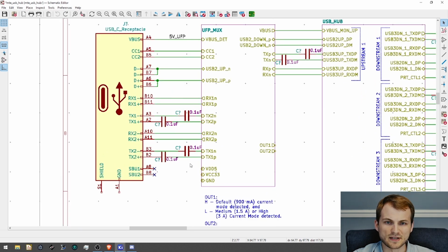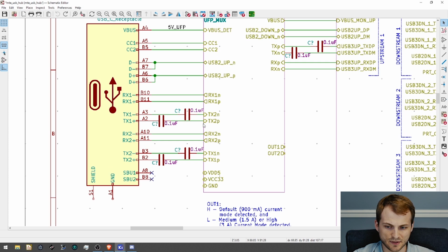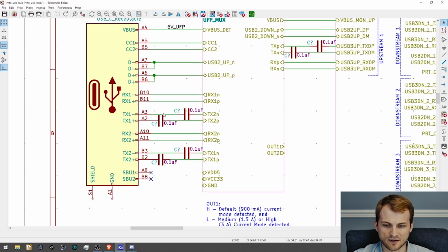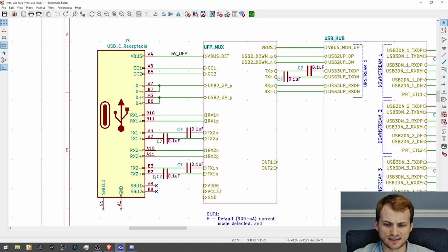So basically, USB 3 and above, which uses the separate differential pairs, have what are called AC coupling capacitors. All these do is block DC voltages. It does a few things. One is it makes sure the data lines are electrically isolated from DC voltages, so it prevents you from getting any ground loops between these.